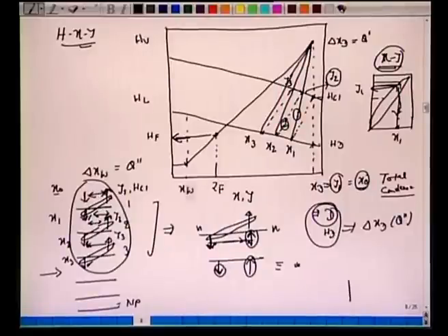Let's do it again. Vapor, alright, and the liquid like this. So these are the operating lines, and the vapor which leaves and the liquid which leaves, that's an equilibrium line, that's a tie line, and this is a solid line. So one time tie line, one time solid line, we connect all these points, and if you keep on connecting, then we have one more. So we have 1, 2, 3, 4, 5, etc. Connect with this. We will get a total of 6 plates.